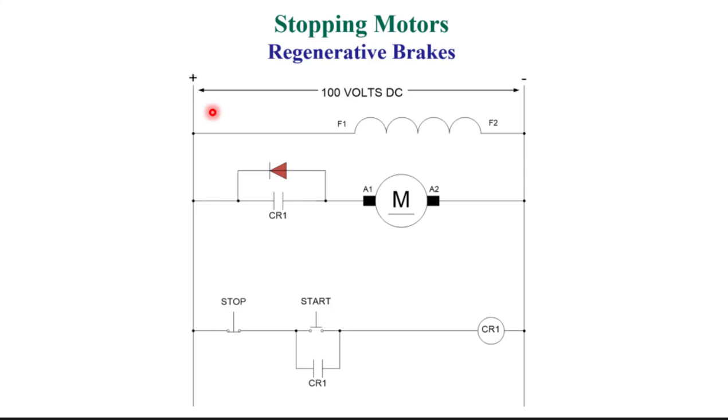I'm going down the highway in my electric car, and I let off of the accelerator, and now instead of applying brakes, which I can still do, friction brakes, the vehicle's going to slow because I'm going to use that inertia as a generator to feed back not into the line, but to the battery. So this is actually going to recharge my battery. The power that I took from the battery to run my electric car, now when I'm off of the throttle or applying the brakes, I have added generation that's putting those electrons back into the battery.